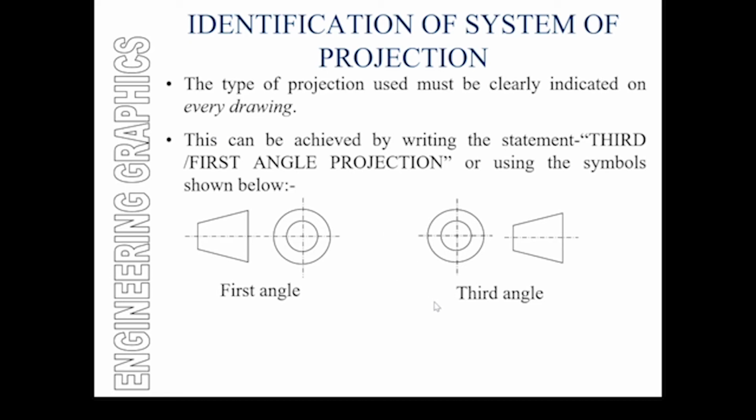I was referring to this particular symbol here, so expect to see this symbol every time there is a third angle projection system. This is what you're also expected to provide every time you produce a technical drawing, just to educate the reader which projection system you're using. Now if you think about it, the third angle icon here is actually a drawing produced in the third angle system, which I find quite easy to understand and remember for future reference.